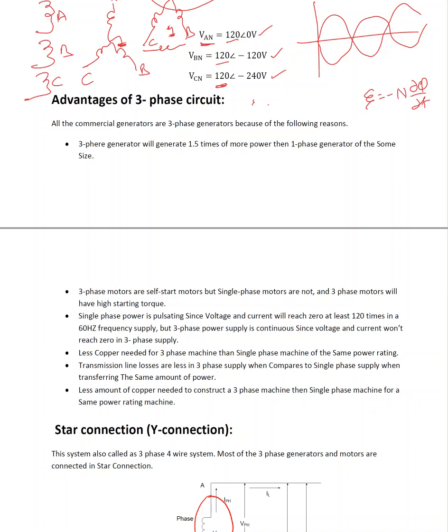So it gives you a rotating magnetic field. Whenever there is a rotating magnetic field, the motor automatically starts. When it comes to single phase, it's an alternating magnetic field. Since it's an alternating magnetic field, it won't self-start basically. That's the reason all the single phase motors either use a capacitor to start or use split phase. Okay, another important point, single phase power is pulsating, since voltage and current will reach 0